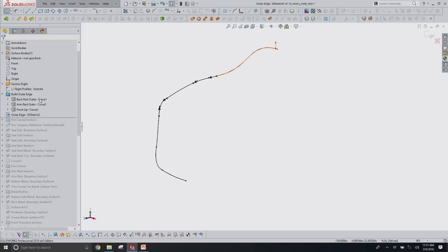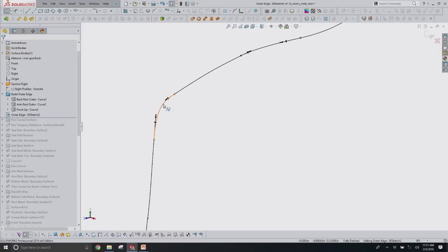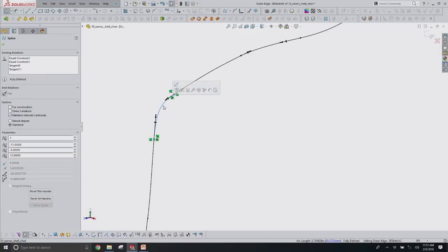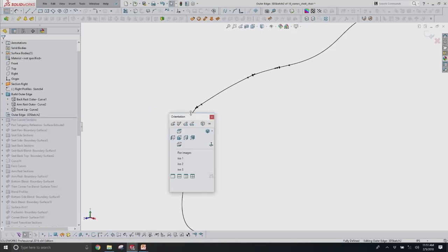I convert the projected curves into a 3D sketch, and if you are creating transitions in the 3D sketch, I always default to the original classic spline tool. Why? Because it's only defined by its handles. So I've added equal curvature here. The style spline tool is great. It has really smooth curvature, as we saw before, but all those additional little control points can be a huge pain to try and manipulate in 3 dimensions and really control the shape of the curve.